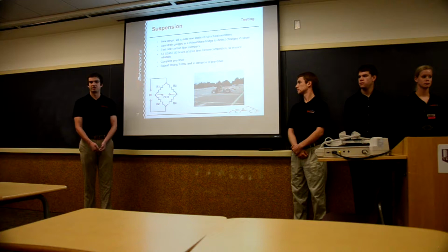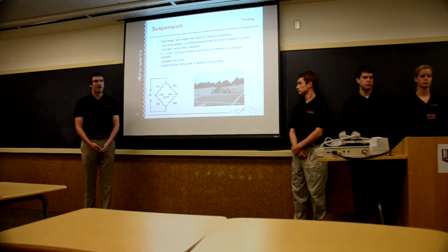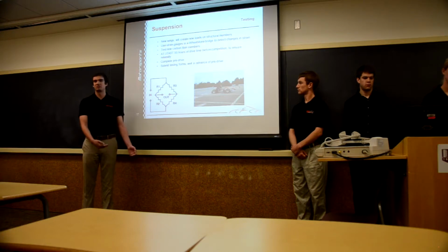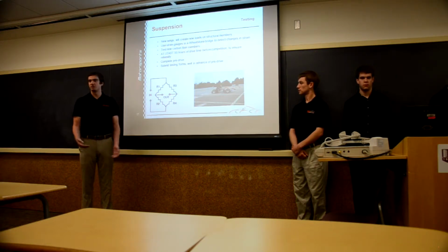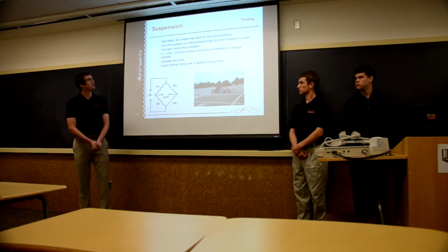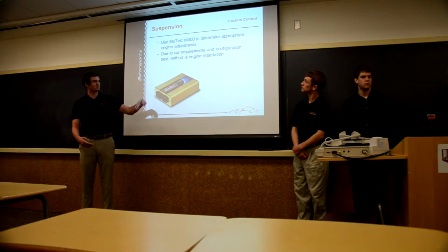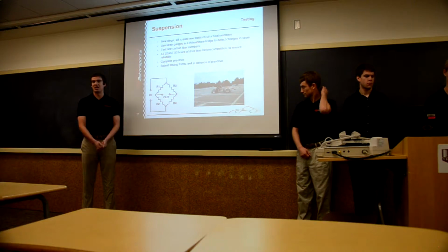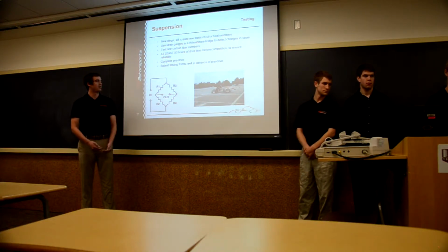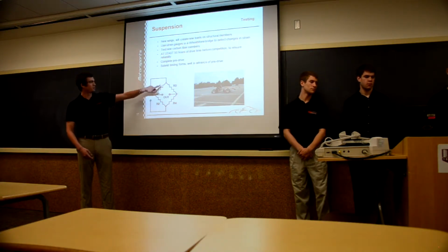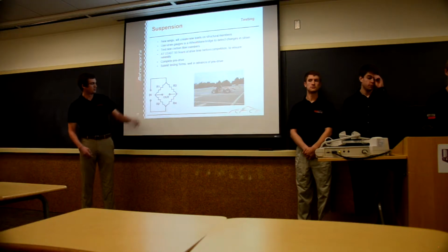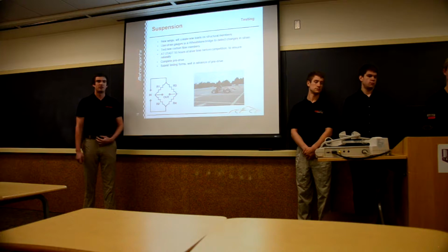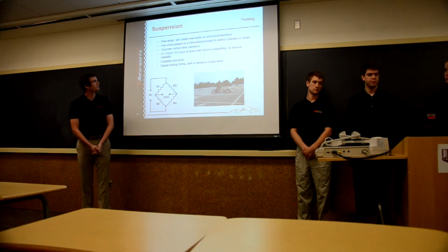Everyone has to complete their pre-drive, each subsystem, as well as every team submits requests for what they would like to test on, and that's also incorporated in pre-drive. There's also structural testing. With the new aero loads going into the chassis, those are going to be tested, and that's done by using strain gauges in a Wheatstone bridge formation, and the changes in the output are used to determine the strain that's new to the car.